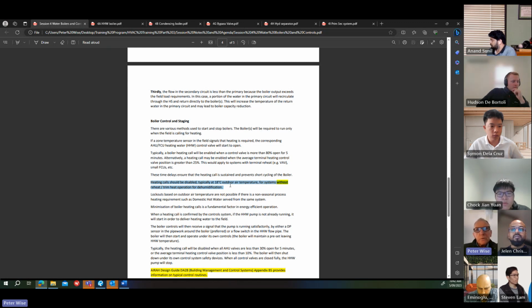So when you put the air through the cooling coil, the humidity is reduced substantially. In some cases you need further dehumidification, and you might put the air through a heating coil to reduce the humidity even further.